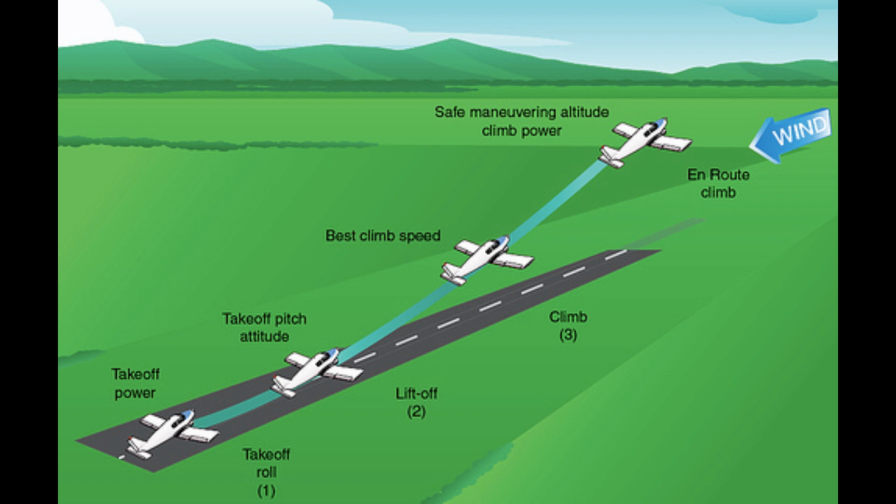If it is necessary to level off at an intermediate altitude during climb, advise ATC. When ATC issues the instruction, expedite climb, this normally indicates that the pilot should use the approximate best rate of climb without an exceptional change in aircraft handling characteristics. Normally, controllers inform pilots of the reason for an instruction to expedite.